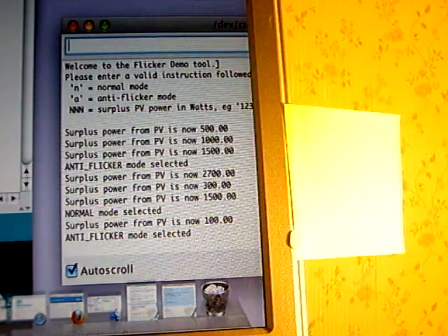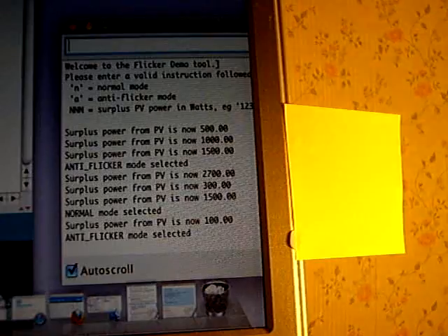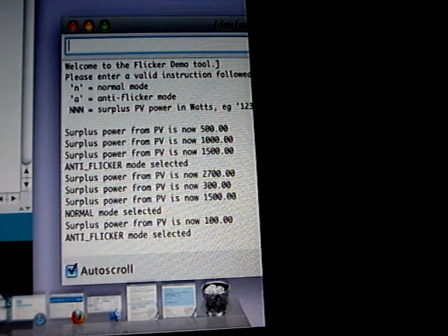So by putting in this simple second threshold and moving between the two on a hysteresis basis, we've slowed down the flicker from 20 Hertz downwards, to about one cycle every 2.3 or 2.4 seconds, so that's only 0.4 of a hertz or something like that. So the flicker is never greater than about 0.4 of a hertz if you're using this new mode.